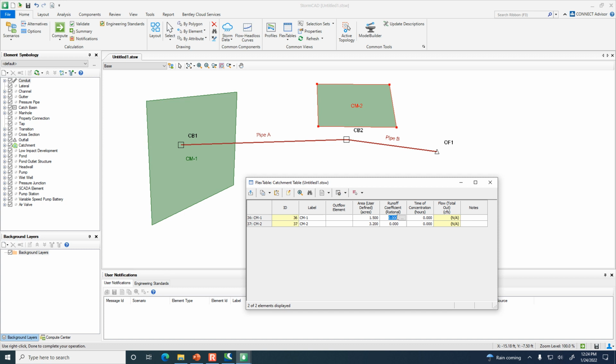The runoff coefficient, that's the C value, so 0.075 and 0.55. Now look at the units for time of concentration. It says hours in that table. What units do you have in the example? Minutes. So, I mean, it's not like rocket science to make the conversion between minutes and hours, but if you had like 3 or 4 dozen catchments, it would be more convenient just to be able to type it in as minutes rather than have to do the calculations.